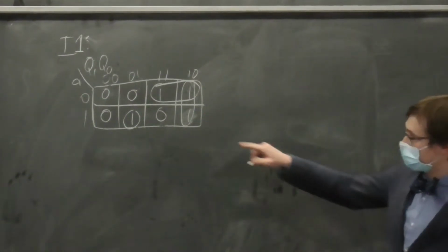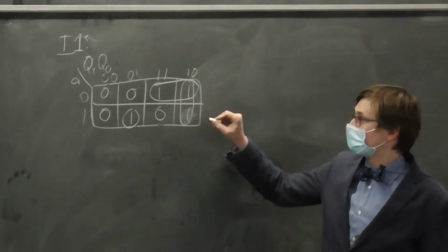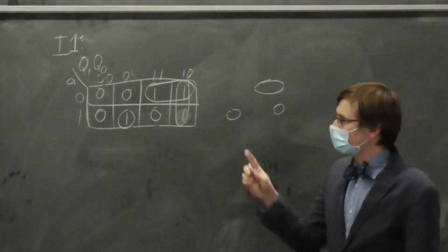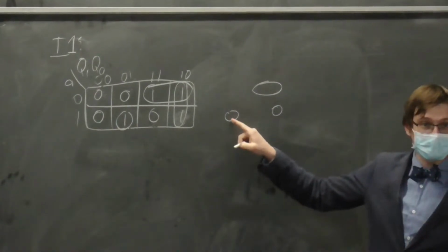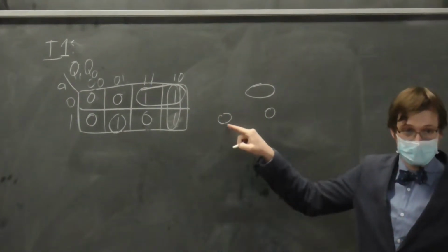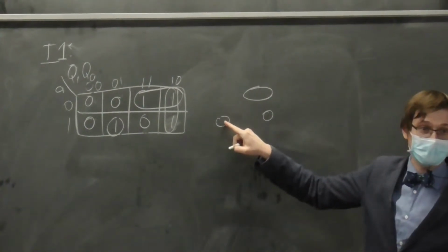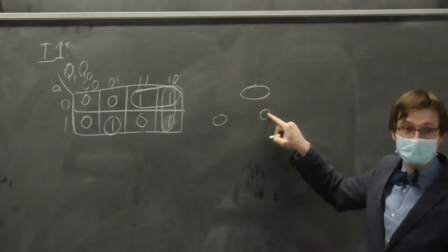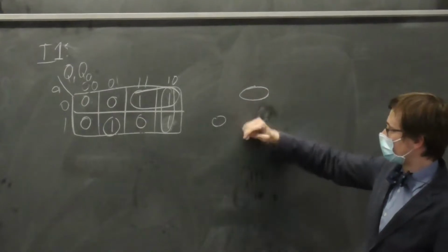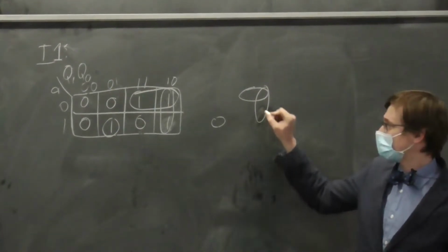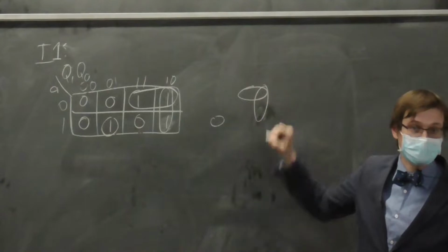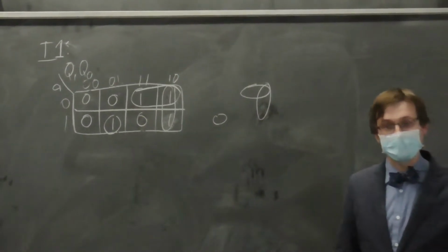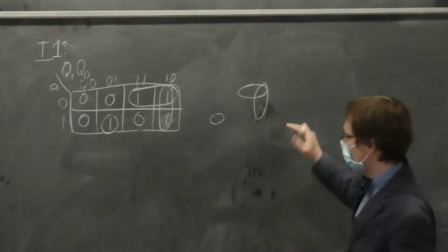So if we were to specify just this guy, right? If we were to draw it like this, and then that, in terms of the logic, the sub-logic circuits, these guys require 3 inputs. These guys require 2 inputs, right? So you still need 3 components in total, but if you blend it across like that, this guy can be represented with 2 inputs, which makes the underlying logic gate itself slightly simpler, right? So it's actually a good approximation thing, right?